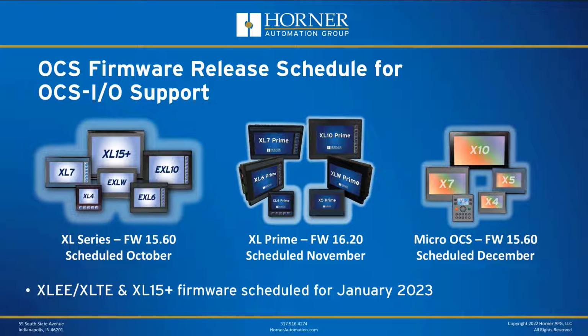Yeah, in that particular sense, a lot of it comes down to performance and resolution, which in most strain gauge applications is really everything. So in terms of high performance or high resolution, that millivolt input may not necessarily allow for those particular applications, or again, high speed applications. But just in terms of a standard weighing application over a period of time or anything like that, it could be something that's definitely used.